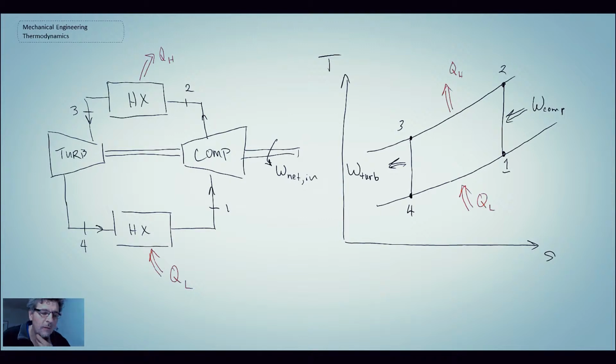So there's our process schematic and process diagram. Going through and looking at the cycle, we start off with air. It could be at atmospheric temperature and pressure. It could be a slightly different condition. But we go through a compression process, and after the compression process, the air heats up. We do work on it. It then goes into a heat exchanger at state 2, and then that comes down to state 3 after we reject thermal energy or heat to the surrounding environment, and so that's what's going on there.